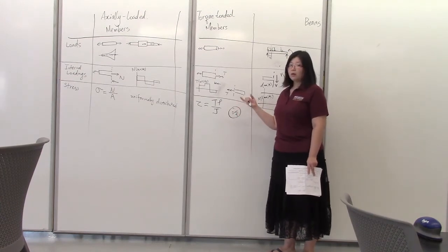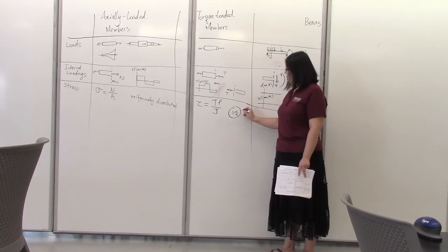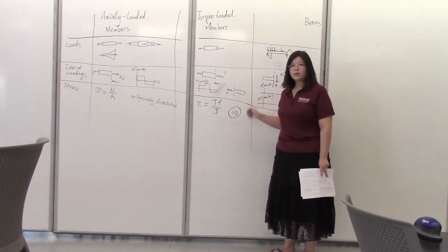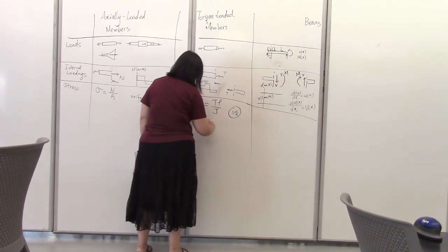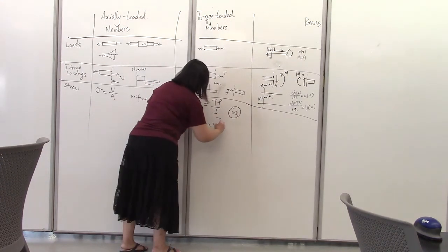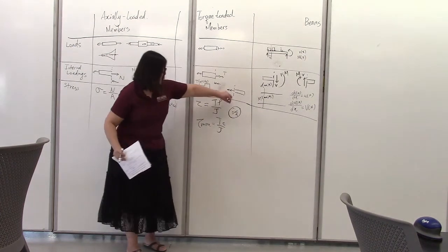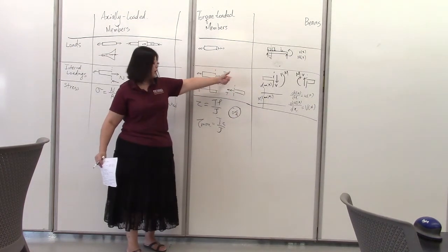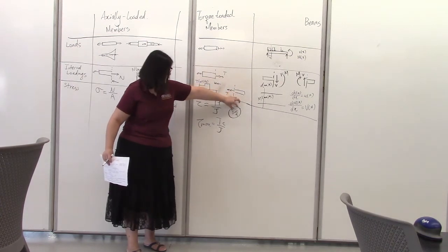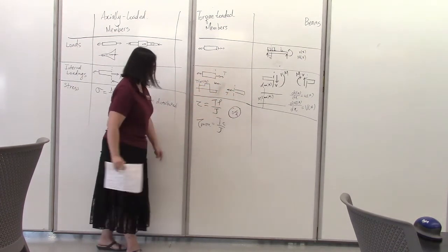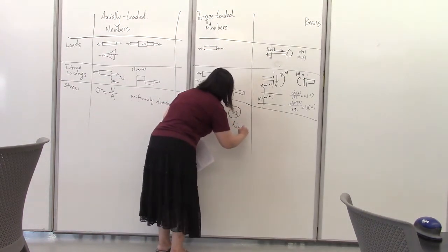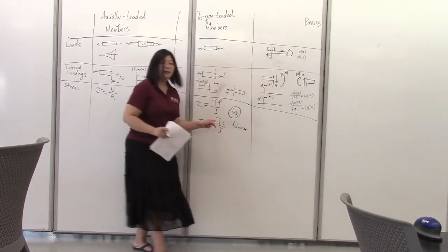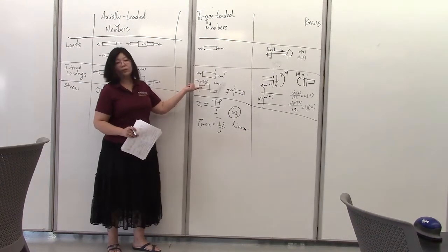So the shear stress on a cross-section reaches maximum when your rho becomes a maximum. That is, when your point falls on the outer surface of the cross-section. And in that case, we say that we have a maximum shear stress on that cross-section, which is Tc over J, where c is the maximum radial distance you could have from the center to a point on the cross-section. In this case, that would be the radius of the cross-section. Okay, that's why we have a linear distribution. In this case, again, T is an internal torque, which should be obtained using method of sections.